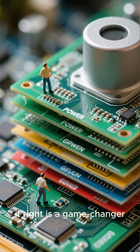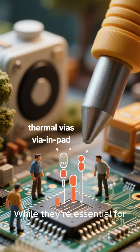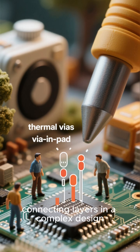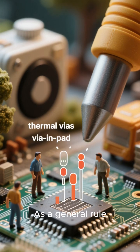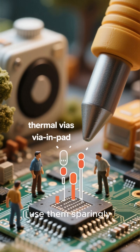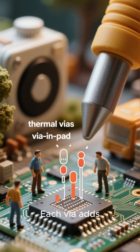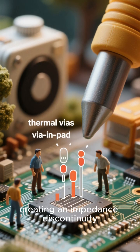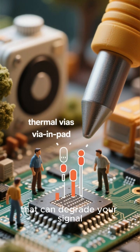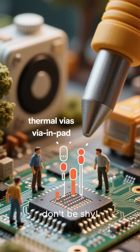Vias deserve their own special attention. While they're essential for connecting layers in a complex design, they can also be a source of problems. As a general rule, use them sparingly, especially on high-speed signal paths. Each via adds inductance and capacitance, creating an impedance discontinuity that can degrade your signal. However, for power and ground connections, don't be shy.